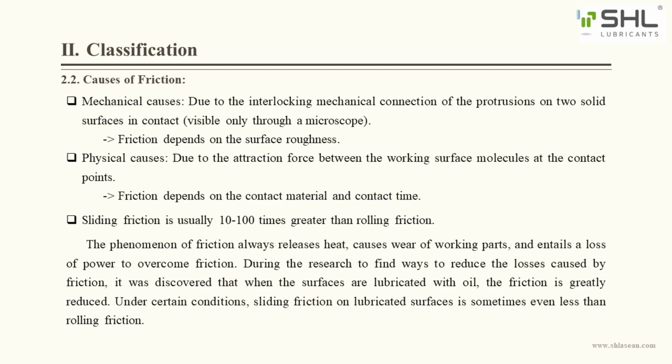Sliding friction is usually 10 to 100 times greater than rolling friction. The phenomenon of friction always radiates heat, which causes wear of the parts and reduces the effort to resist friction. In the course of research to find ways to reduce friction loss, it was discovered that when surfaces are lubricated with oil, friction is greatly reduced. Under certain conditions, lubricated sliding friction is less than rolling friction.